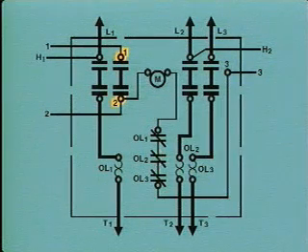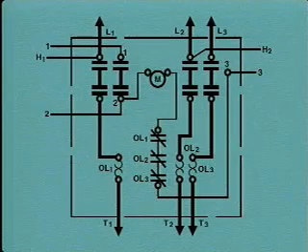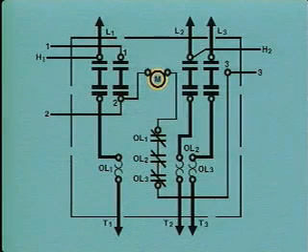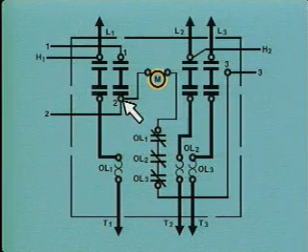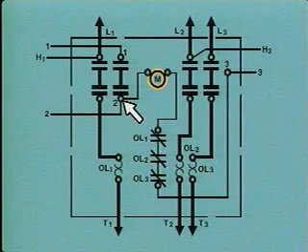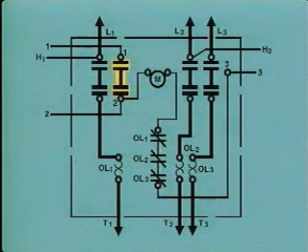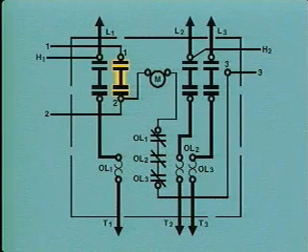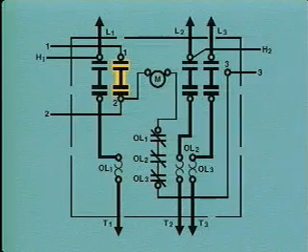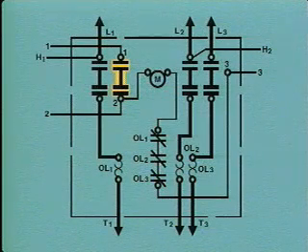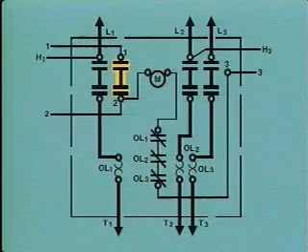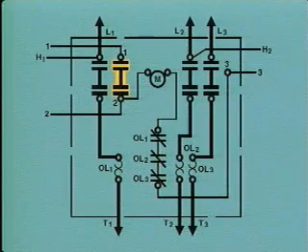These numbers correspond to the numbers on the schematic diagram, and they can be used as a reference during troubleshooting. As on the schematic, the M coil is represented on the wiring diagram by a circle with the letter M inside of it. One side of the M coil is connected to maintaining contacts and the start button at connection point 2. Although the maintaining contacts are in the control circuit, they are represented with heavy lines. This is because, like the main contacts, they are operated by the M coil. There are 2 sets of maintaining contacts in the controller, so the wiring diagram represents both sets.